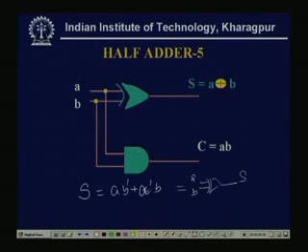And AB, the same input I am taking, then C equal to AB. Now, what is the advantage or disadvantage of that? See, first thing is, here there is no need that complemented variable should also exist, only we have taken the uncomplemented variables, and there carry is simple AB and one XOR function. So, only there are 2 gates, but just notice that here this XOR is not a basic gate,